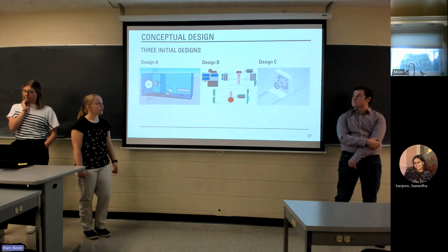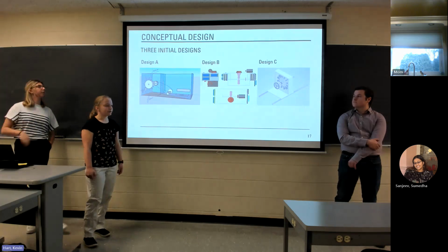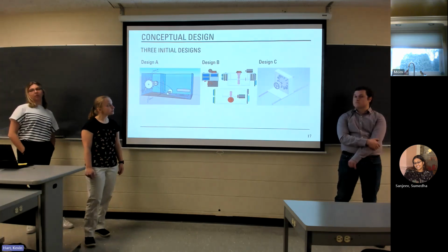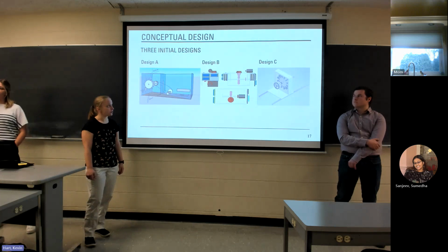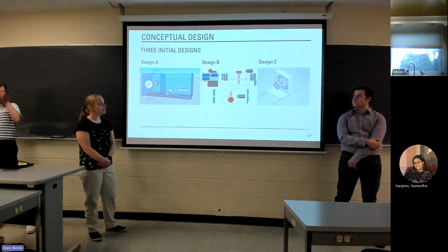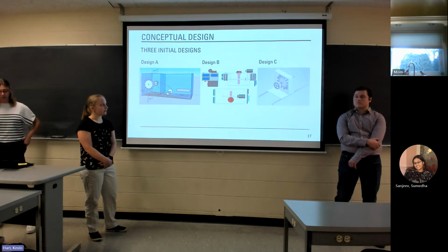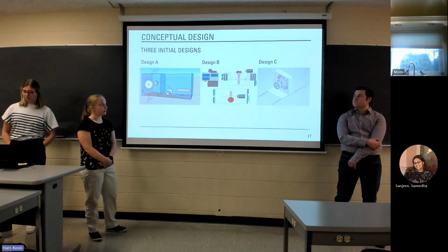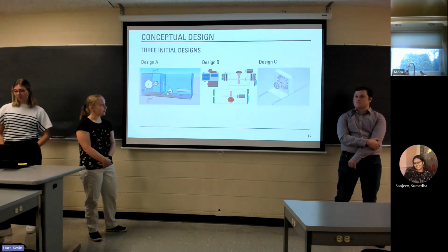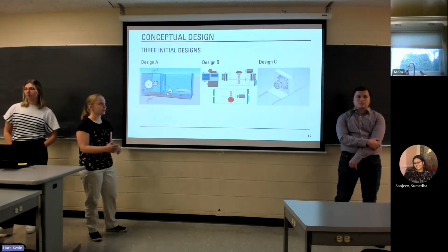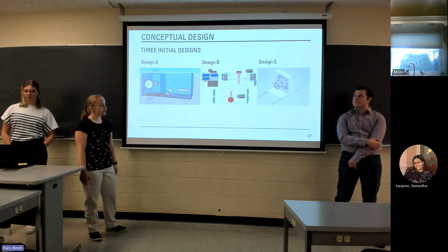It also features a driving water jet coming in from the side and a brake jet coming in from the top. Moving on to design B, that would clip over the sides of the tank. It only had a driving nozzle and no means of braking. The motor, generator, and hex shaft in the center, which connect to the wheel, were connected by a pulley, and it was not fully contained, but had a splash guard on the sides and top to prevent splashing.